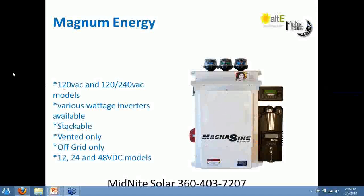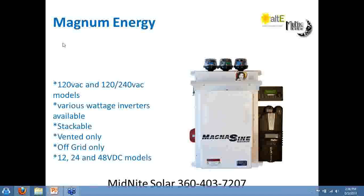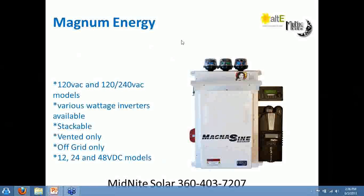So again, you do need that backup panel because the loads do need to be separated. Just because you cannot backfeed the main panel, you will end up backfeeding the grid and could possibly kill somebody doing something like that. More likely you would actually blow up your inverter, probably would never be able to power the grid just because it's so big.